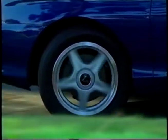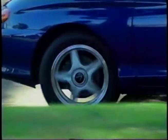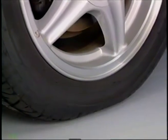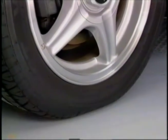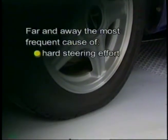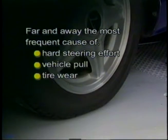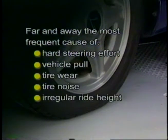The area that is most likely to be misdiagnosed as a problem with a steering or suspension component is wheels and tires. Start your diagnosis of any steering or suspension concern by simply checking the tire pressure. Far and away the most frequent cause of hard steering effort, vehicle pull, tire wear, tire noise, and irregular ride height is simply low tire pressure.